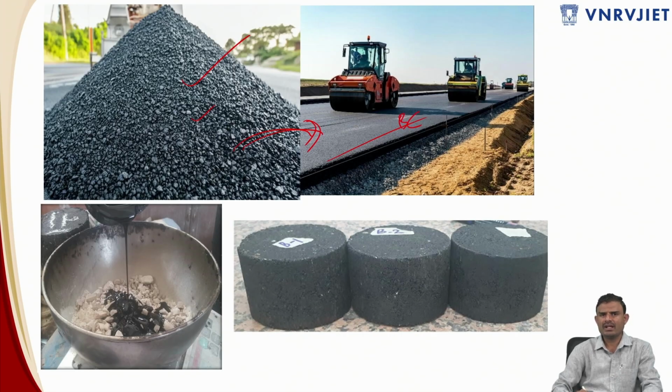Now we are going to see how this bituminous concrete is going to perform in field conditions. Before that, you have to do the test, and you have to give some design, that is, the mix design, and you have to generate a job mix formula. For that we have to conduct a test, or you have to prepare a mixture in the laboratory conditions. You have to take the mineral aggregate of different gradations or different sizes.